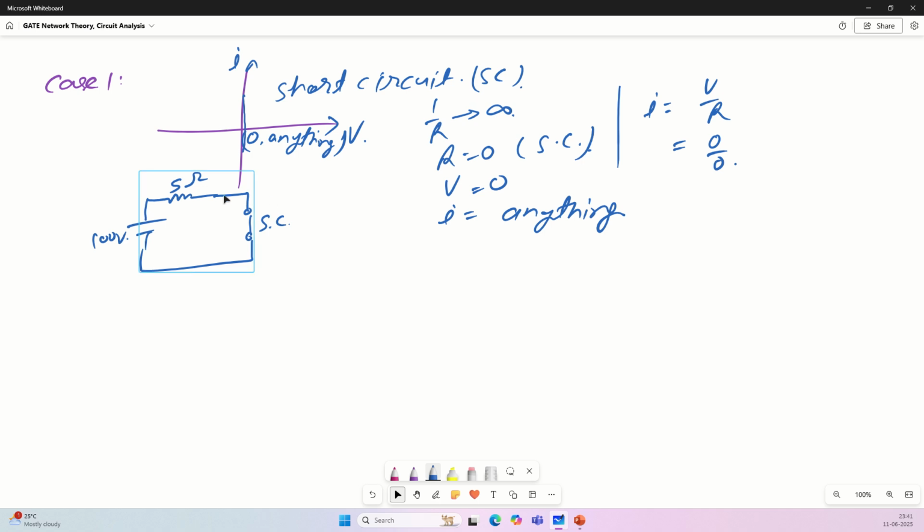But still, even if you directly connect this wire, this circuit doesn't go into a catastrophic form. Why? Because the source has its internal resistance, which saves the circuit from an infinite amount of current flowing through it. So that is the understanding that you should have.